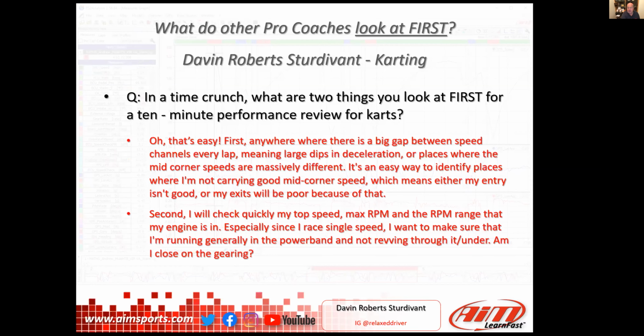Here, I didn't want to leave the karting people out. I have a tremendous respect for Davin Sturdivant. He's really a wonderful soul and a great teacher and a great explainer, and very humble about what he does. I'm not a kart expert, but this is priceless information. These are pearls of wisdom, just small drops that make a big difference. Here he's saying anywhere there's a big gap between speed channels every lap, zoom in on that. I didn't realize it, but he said if I'm sliding the kart too much, I lose speed that I can't get back. So it can be a problem for whatever reason.